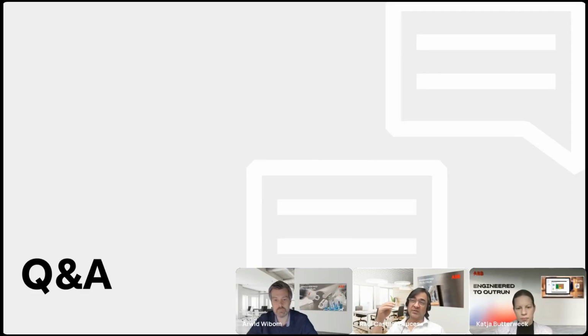So normally it is recommended, when one starts up the web app, to use these API functionalities to become aware of which grants are available, and then based on that you can influence your individual elements by showing or hiding them. Each element has its own function called hide or show, and with that you could really hide part of your HMI depending on the grants that you have.